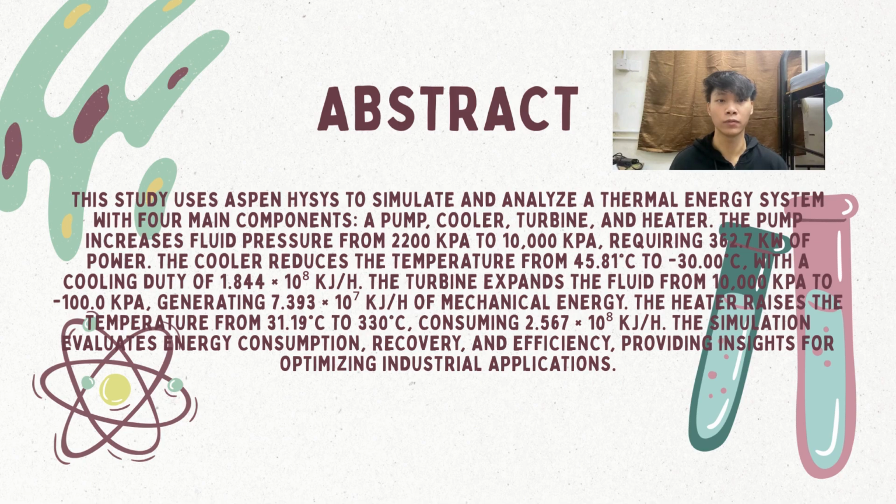The turbine expanded the fluid and generated a significant amount of energy, while the heater raised the temperature from 31.19 degrees Celsius to 330 degrees Celsius. Overall, this simulation gave us important data about energy use, recovery, and system efficiency, insight that can help improve real industrial operation.